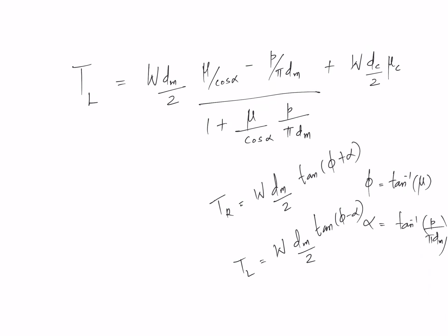But now they are asking us how you will evaluate efficiency. See, what is efficiency? Efficiency is nothing but output divided by input. Assume that you are working with a power screw and you are rotating your power screw by 1 turn. What is the work you are doing? That is the input, right?